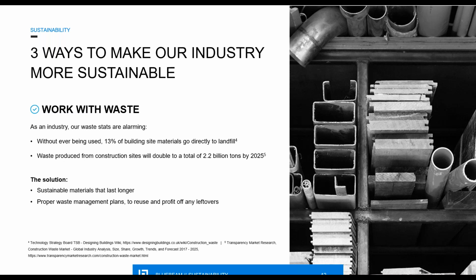We're seeing things like porous concretes, a concrete that actually absorbs pollutants from vehicles, and even by nature of its porous abilities can help with water mitigation and runoff by preventing flooding or pooling or puddling on roofs, etc. Skanska themselves have created a green concrete, which is a low carbon concrete that actually has a 50% reduction in carbon emissions, because they replaced parts of the cement volume with slag and reused and recycled materials. So again, some huge advancements that we're seeing where the industry is really kind of fighting back.